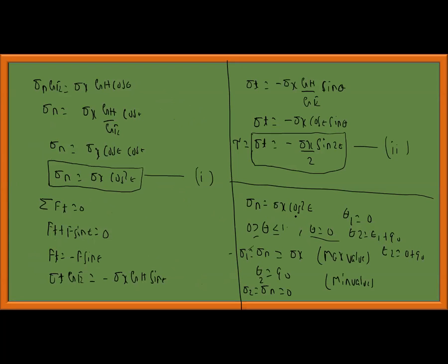Then what is the minimum value of sigma n? You can get it. You can add theta 2 as a theta value. You can think and you can do also. But generally, there are two mutually perpendicular planes, theta p1 and theta p2, the principal planes, which are separated by 90 degrees.